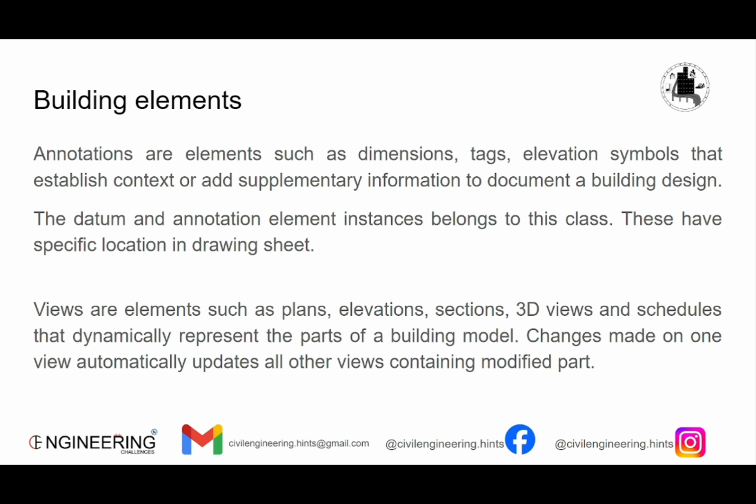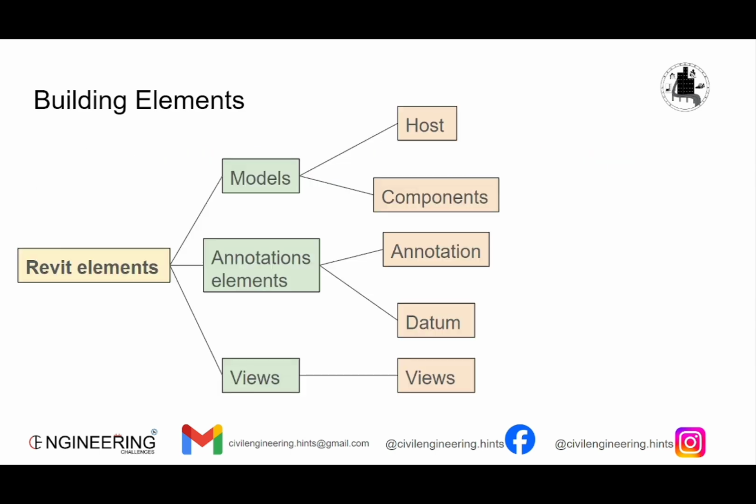If you delete a view, you will lose all the annotation elements placed in that view. View elements do not control the model elements. Please remember this: view elements do not control the model elements. If you delete a view, all the annotation elements that are placed on top of the view will get deleted.